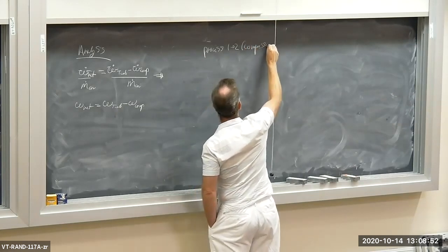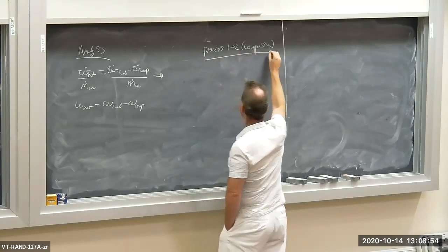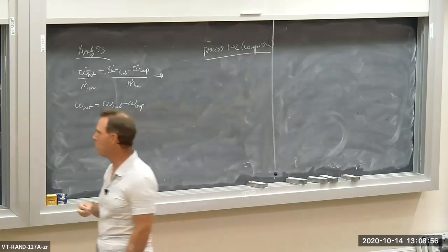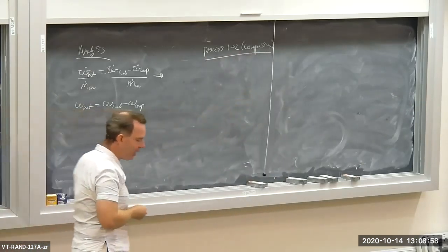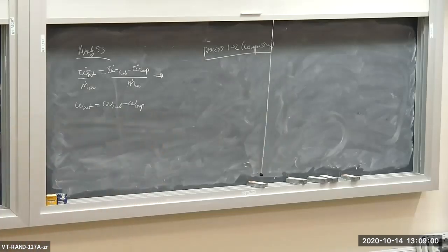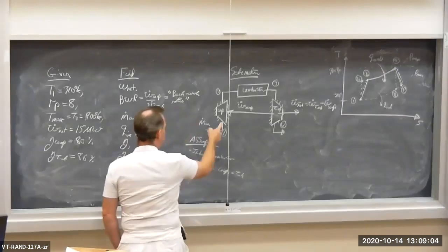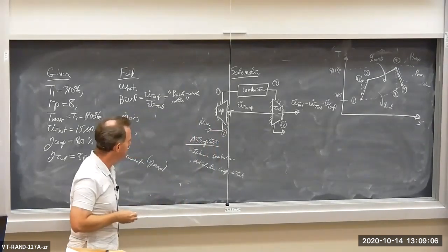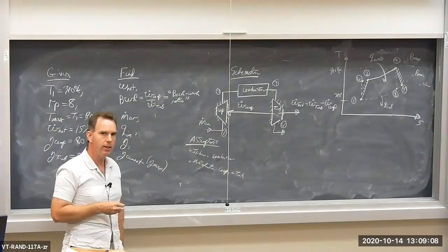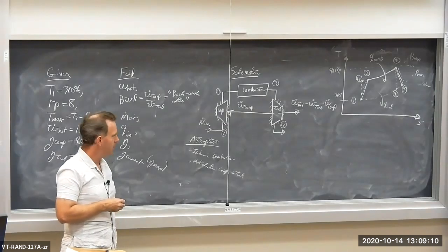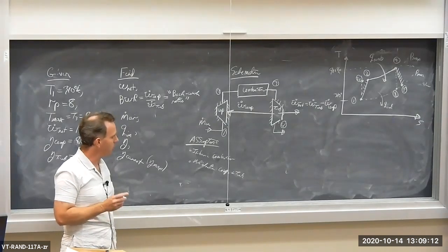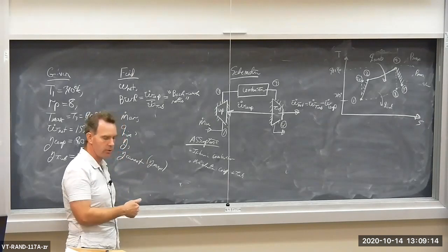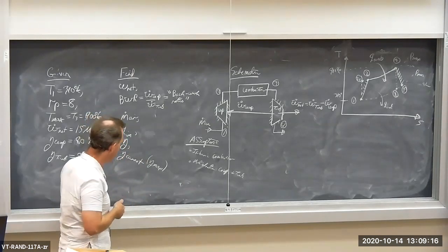Compression. That's the compression process in the compressor. So if I apply the energy balance to my open flow compressor, it's adiabatic. Work is positive, compressor work is positive on the system, not by the system.